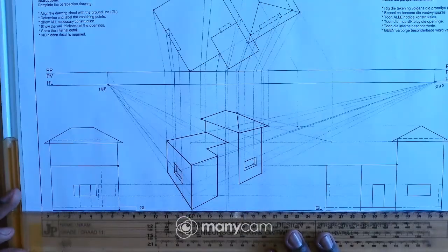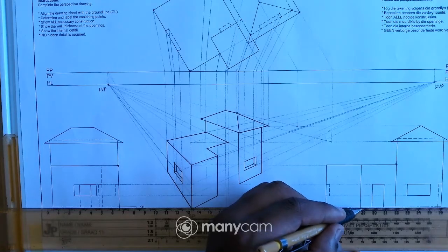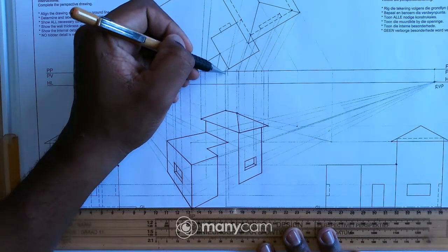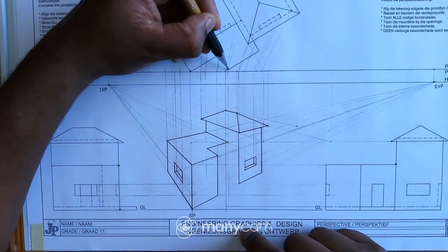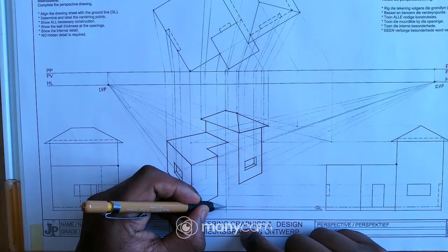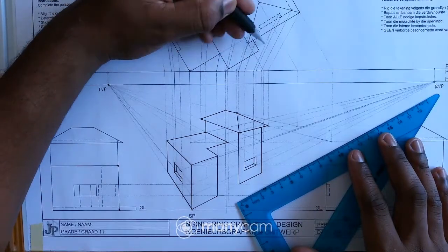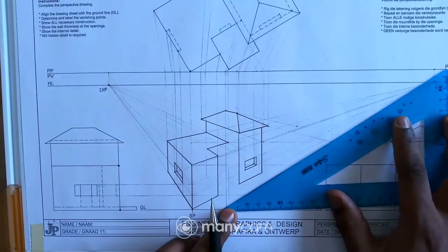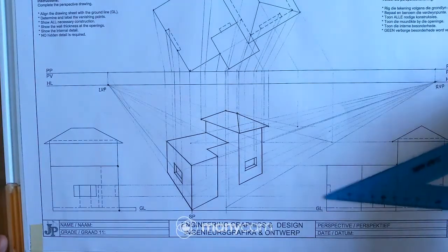Okay, so now my focus will be on that vertical line, and now I'll have to project the height of the stoop to that vertical line. So that vertical line is right over there. Okay, from there, because it's this point, I'll have to take this point to the RVP, because this line goes up towards my right hand side. So I can just take that point up to the right vanishing point.